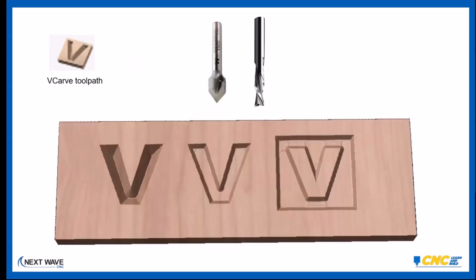And then the third one that is really common is the VCarve toolpath. What's really nice about this is you can very quickly carve lettering or designs with a V-bit to get very decorative shapes as a result. The three designs you have here kind of sum it up. If you understand how these are created, then you have a lot of control over what you can do with your V-carving bit. Now, the one on the left is a full depth V-carving. So you've got the letter V in your drawing, there would be a vector that goes all the way around that V, and you would then carve that out with the V at what's called a full depth.